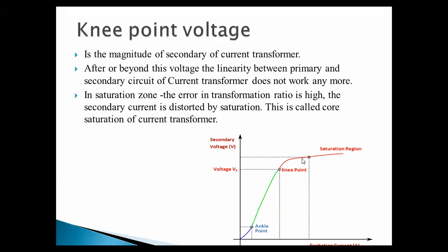But when your core gets saturated, after that if you increase the value of current, the flux will not increase, the flux remains constant. That is nothing but the saturation of that core. The same is here also.